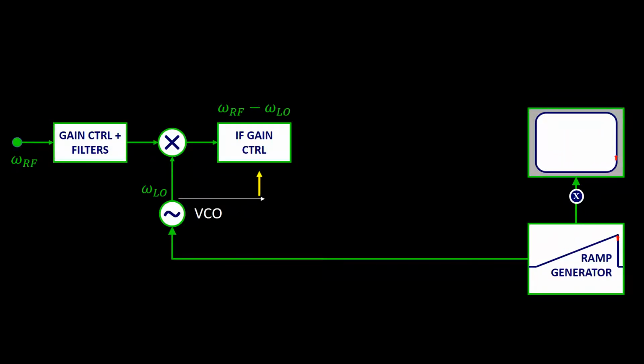A voltage-controlled oscillator is able to produce an output frequency proportional to the input voltage. Therefore, if we use a VCO in the down conversion subsystem that is controlled by the ramp generator, we obtain an intermediate frequency at the output that is proportional to the time. This can be used to make the sweep in the x-axis equivalent to a sweeping frequency. Well, it seems that we have all we need. Now let us check if this works.